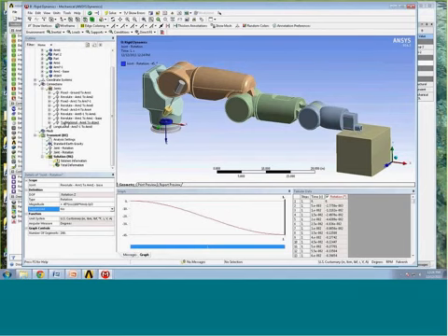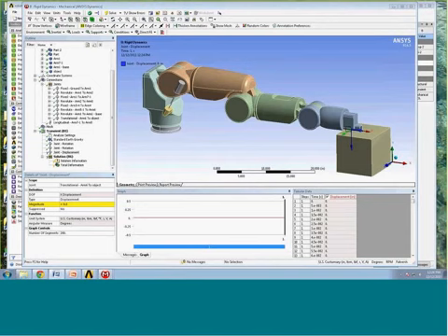And the joint load is going to be in the x direction. The type will be a displacement. And again, I want the magnitude to be a nice smooth curve, so I'm going to cut and paste a quarter sine wave type of curve. Okay, so that's going to assign an x displacement in that joint between 0 and 2 inches.